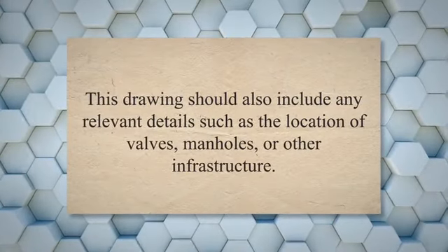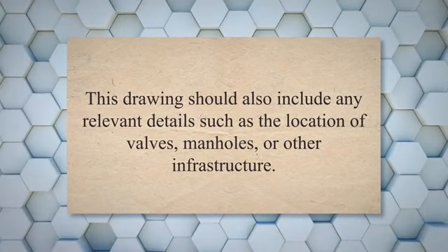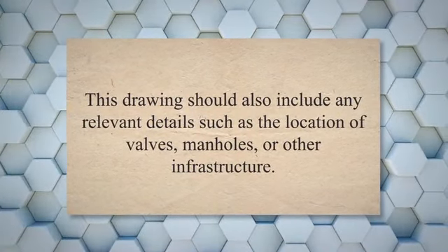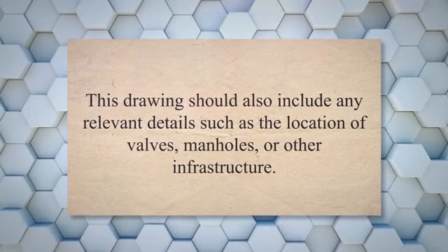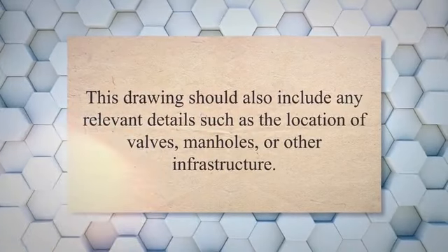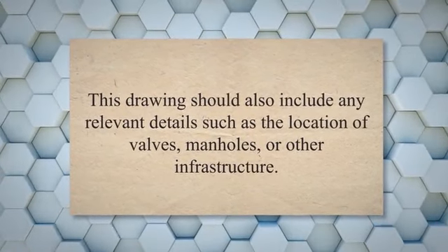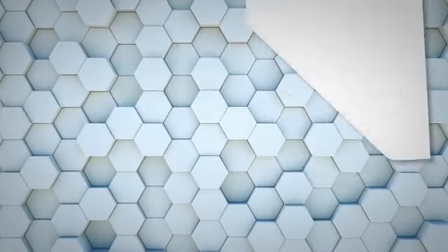Drawing the pipeline route. Using CAD software or another drawing tool, create a drawing of the pipeline route that includes information such as the diameter, material, and depth of the pipeline. This drawing should also include any relevant details such as the location of valves, manholes, or other infrastructure.